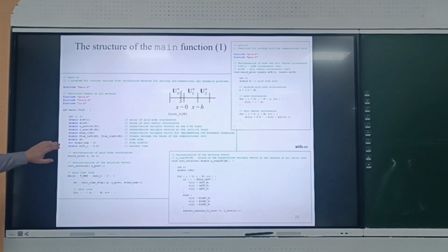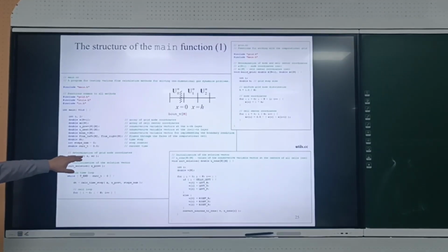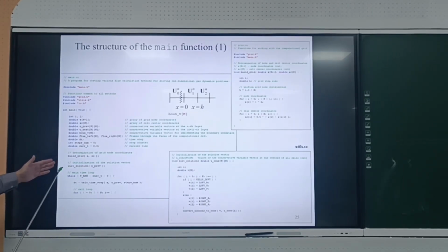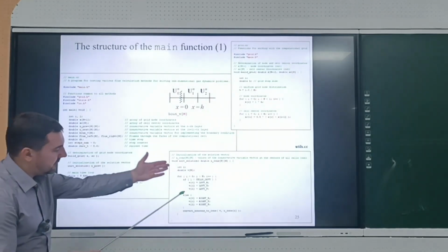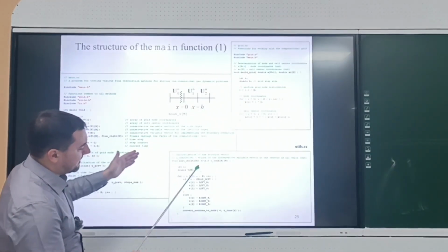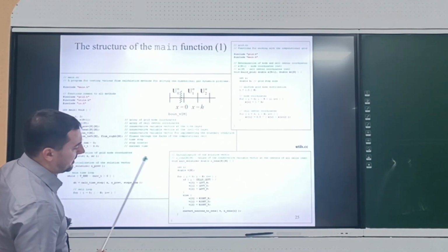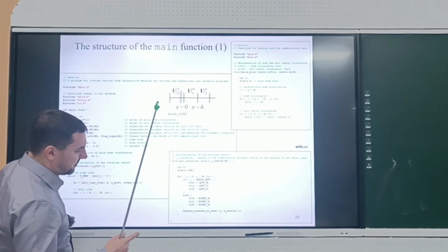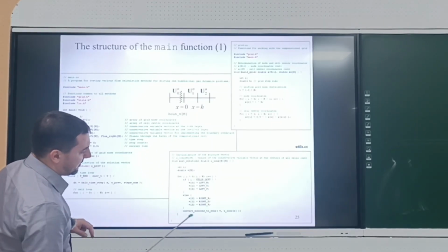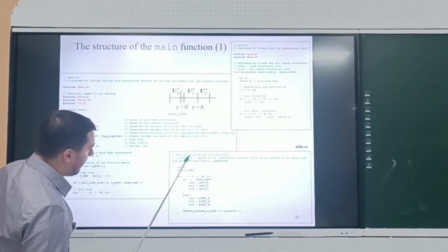So first step, we build the computational mesh. Actually it's just a uniform mesh, so we define the coordinates of our cells and the boundaries of our computational cells. Then we should initialize the solution. In the simplest possible case, in the left part of our computational domain, we set parameters in the driver section, and to the right the parameters in the driven section.